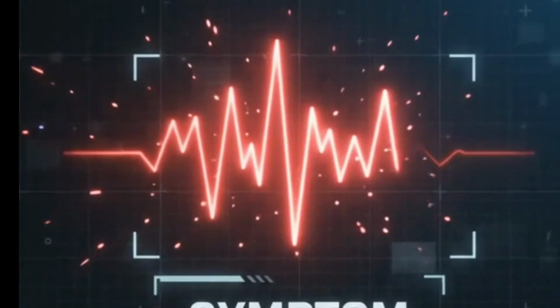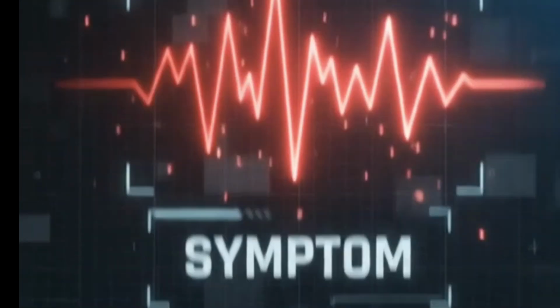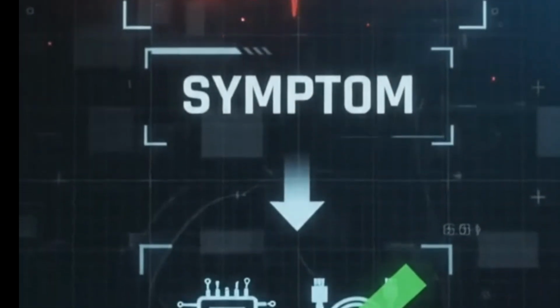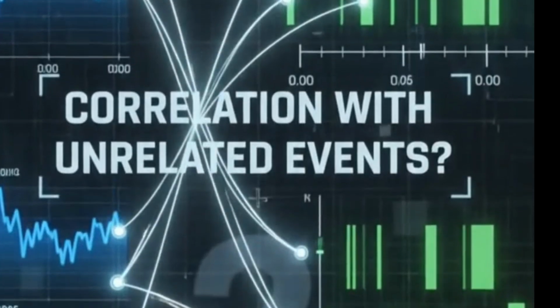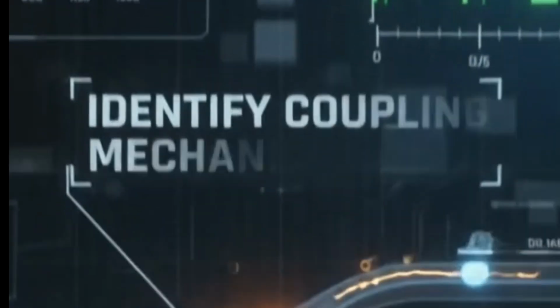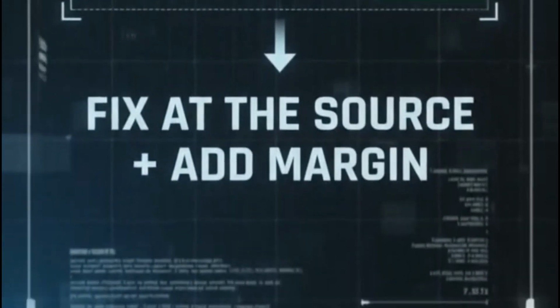Quick recap. Symptom: intermittent faults with no consistent pattern. Root cause: contactor arcing inducing a noise transient into nearby DI wiring. Fix: RC snubber at the source, plus a modest input filter increase as a safety margin.